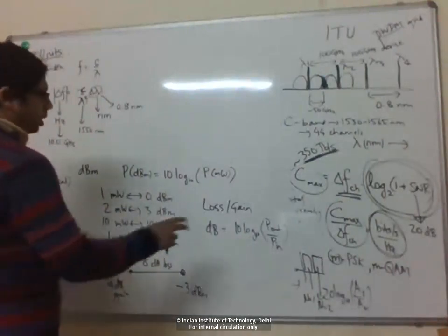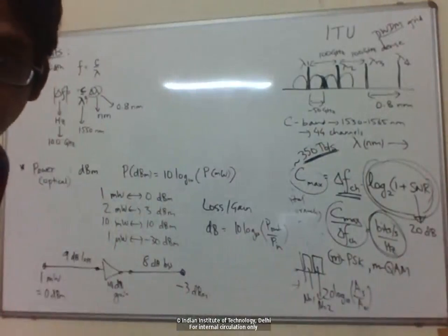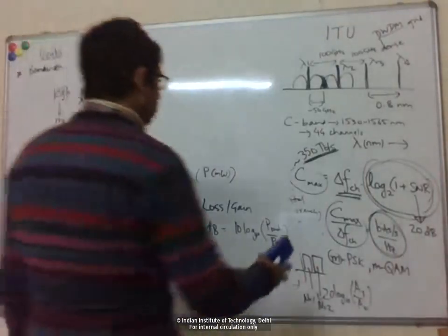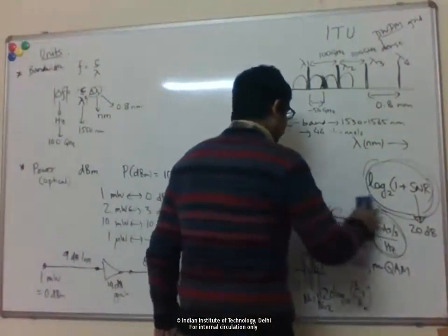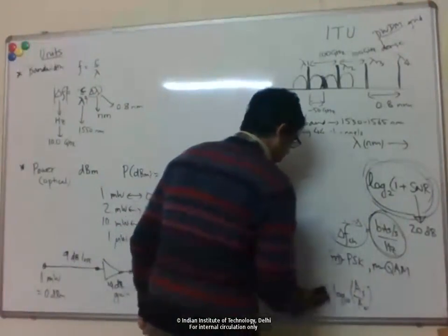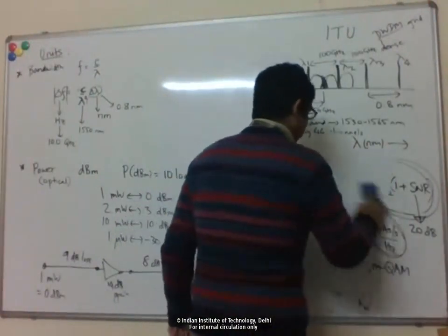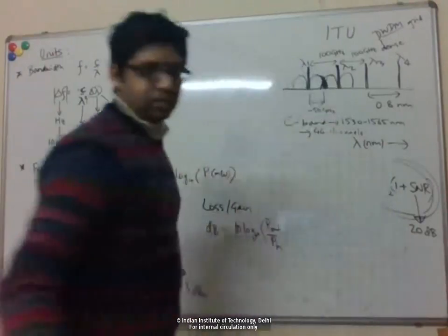Right, so continuing on this dB theme, why can on-off keying not be used for increasing spectral efficiency? So there's a question. We discussed this OOK scheme, and we said that basically the spectral efficiency is just 1 bit per second per hertz. I mean, that's just the modulation. But you could have variations.